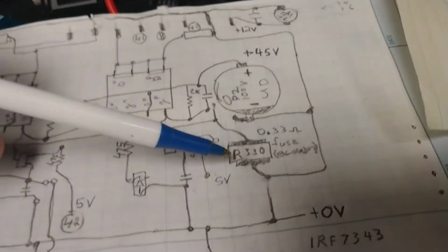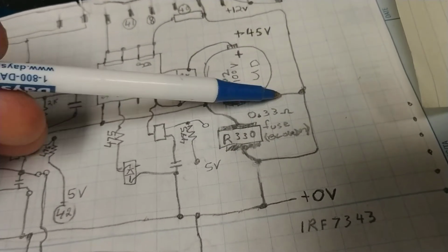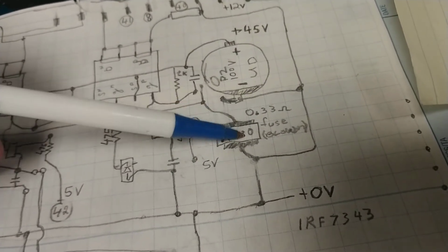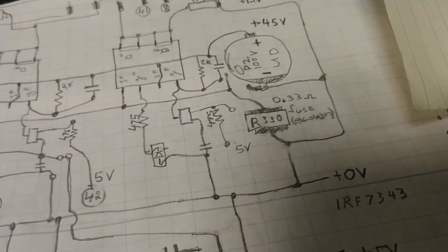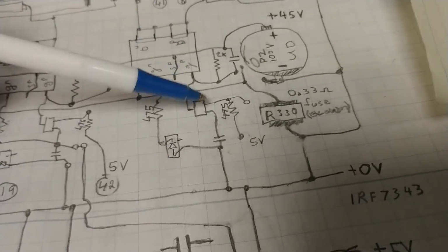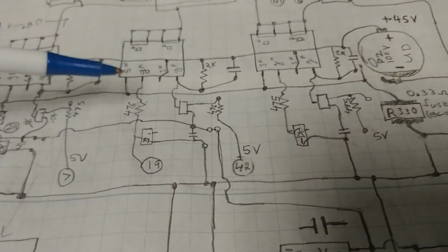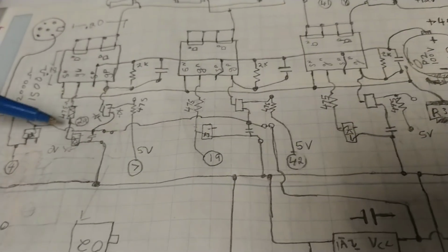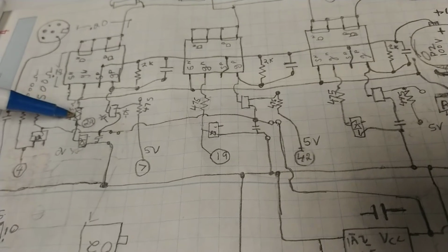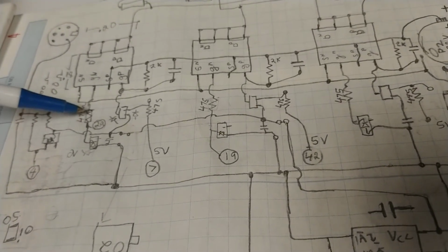Well, that was blown. In other words, it was not reading 0.33 ohms, it was reading a few mega ohms or even an overload on my ohm meter. That was blown. That means I have to go hunt that up and buy it. This resistor had burned, it got hot enough to burn the numbers. You couldn't read the numbers.